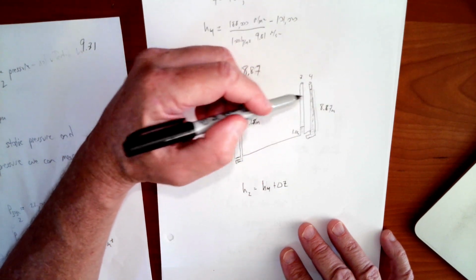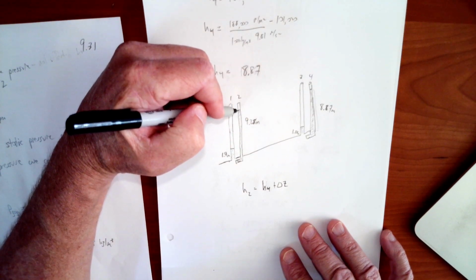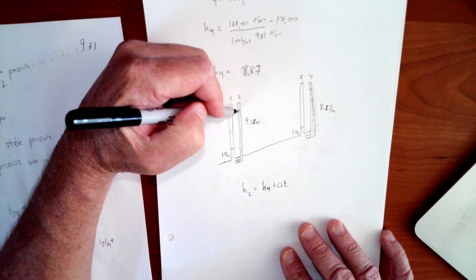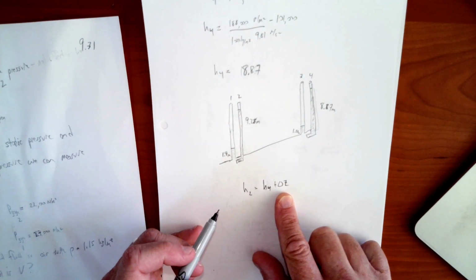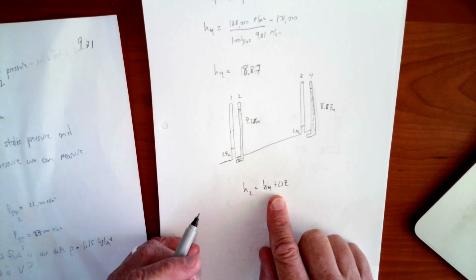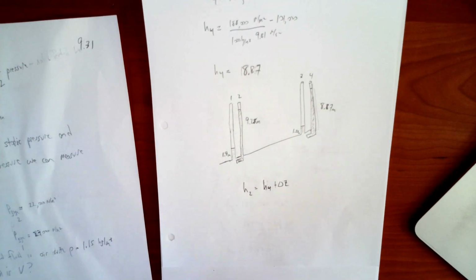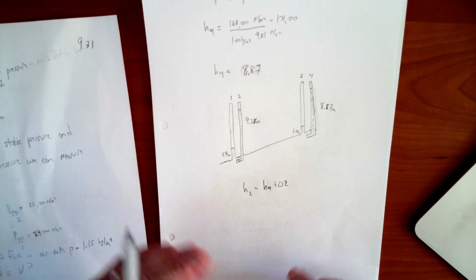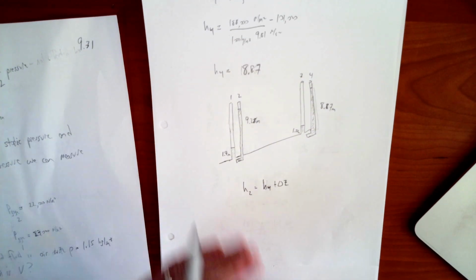It's interesting to note that this height of 4 and this height of 2 in an absolute Z scale are the same. So H2 equals H4 plus delta Z within 0.01 as I've done the calculations, which is simply a matter of a rounding error. So these in fact stay the same. So the total amount of head pressure in the system, or the amount of energy in the system, hasn't changed. It's just reduced its pressure, but it's increased its elevation.